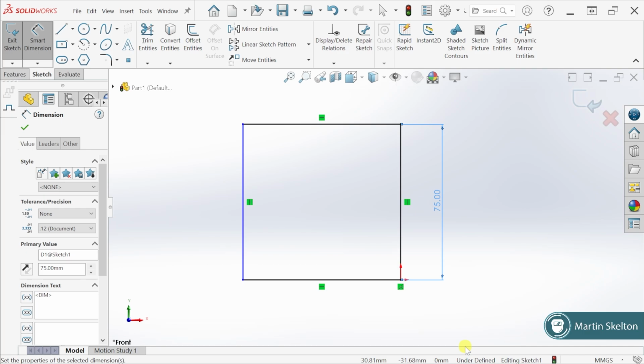But if you're second guessing things like manufacturing drawings or models, that just piles on a lot more stress than needs to be. So before I ever send out any kind of models to be manufactured, I would always make sure that they are fully defined, regardless. Now, there are exceptions to the rule, and we can talk about them later as well.